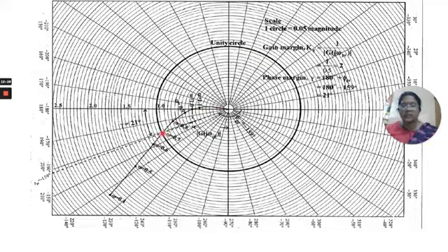Now I am going to plot this polar plot in MATLAB. These are the polar commands in order to plot the graph. I will explain it to you in MATLAB. So this is the program for plotting the polar plot in MATLAB. The first instruction is clear all. This clears all the lines, clears the screen. Then s is equal to transfer function of s. So the transfer function is represented in terms of s by using this command.